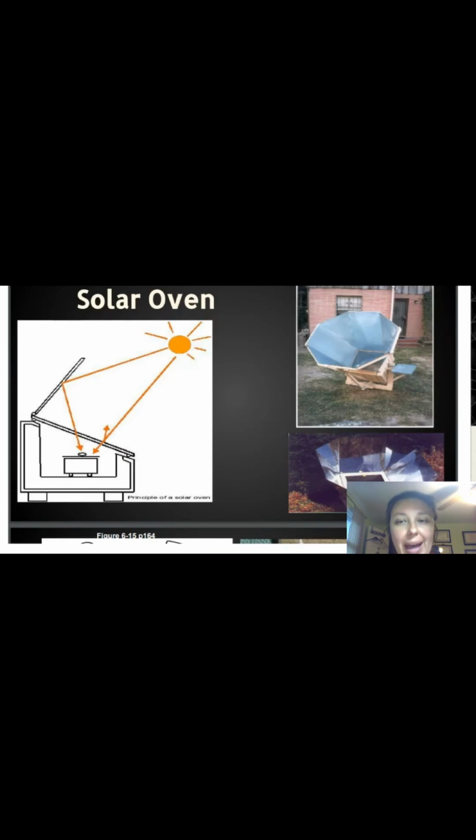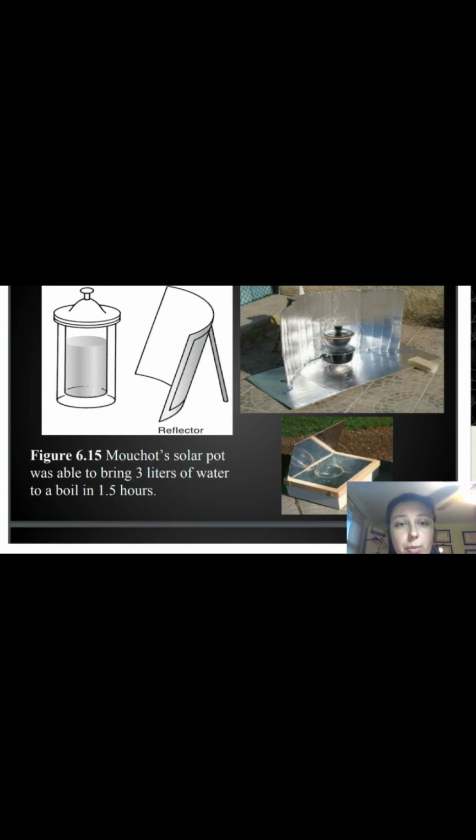So popping back, this one, once again, we can see the concentrating sunlight into the system by using these mirrors or reflective surfacing, right? I'm trapping my heat within my system. And within there, you can actually see these are like a painted black box. You can see this is an insulated black box. We are creating a system where we are converting any sunlight that's in the box into heat. So I'm using a thermal capacity.